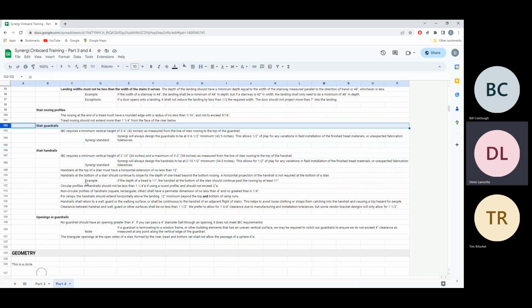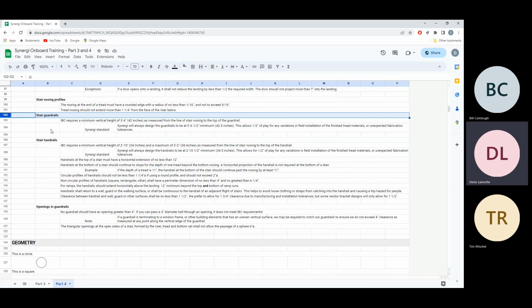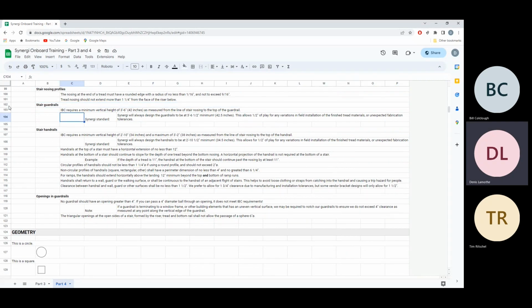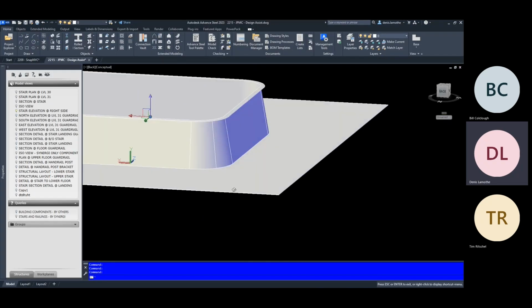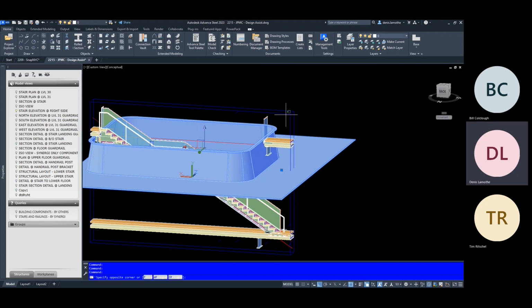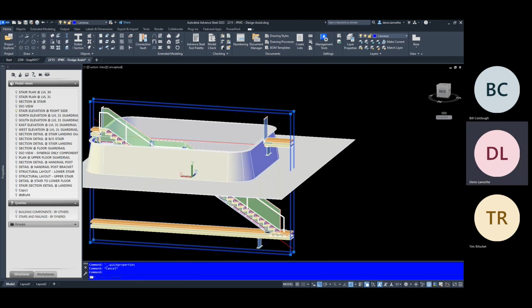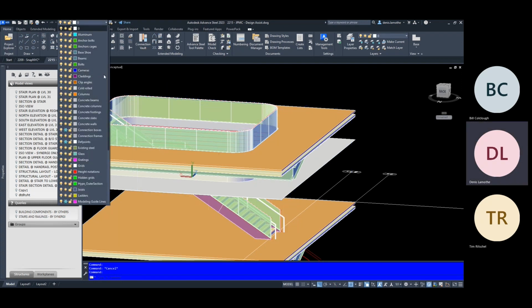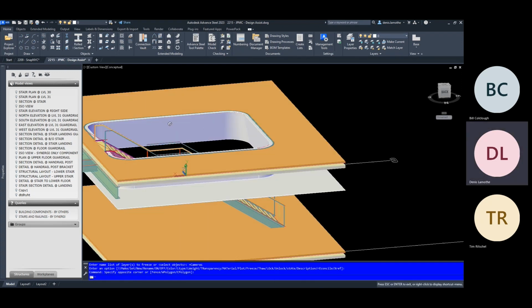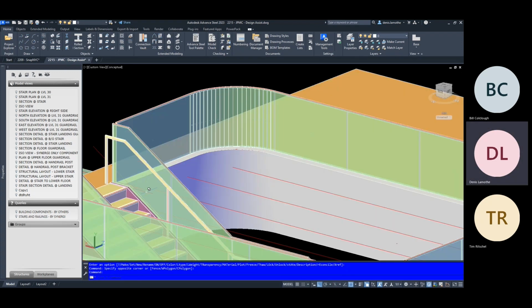Moving on, so that's pretty much the stair structure there. Stair guardrails. Guardrails is going to be an interesting one to talk about. And by guardrails, I think you all know what a guardrail is, right? The glass railings that you see on a stair and floor openings. There we go. Let's just hide those camera views because that's a lot of camera views. So building code for a railing, whether it's at a stair or a floor, is 3'6", measured either from the top of the finished floor, or from the nosing line on a stair.